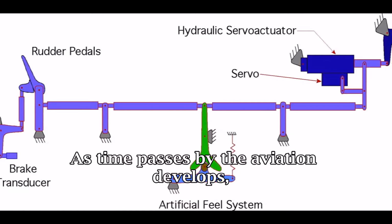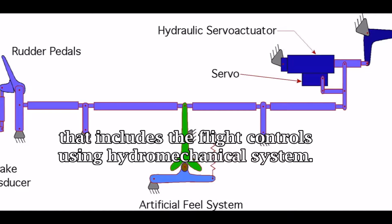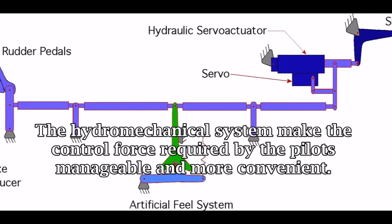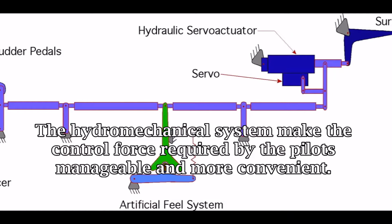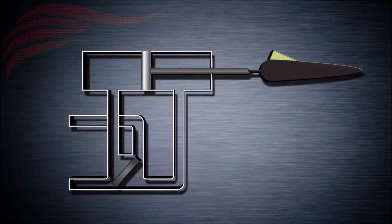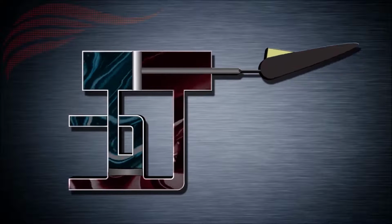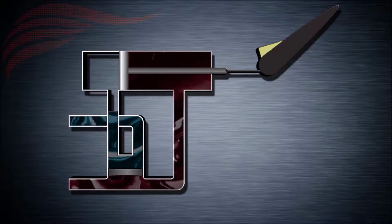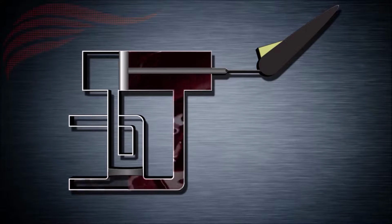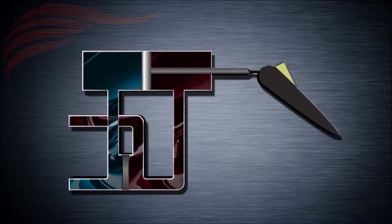Time passes by. Aviation develops. That includes flight controls using the hydromechanical system. The hydromechanical system makes the control force required by the pilots manageable and more convenient. A selector valve rotates through 90 degrees to route hydraulic fluid to either side of the piston head to move it back and forth. To pitch the aircraft up, the pilot pulls back on the control column and the elevator will move up accordingly. When the control column is moved back, the hydraulic fluid is pumped under pressure into the actuating cylinder, forcing the piston backwards and lifting the elevator.